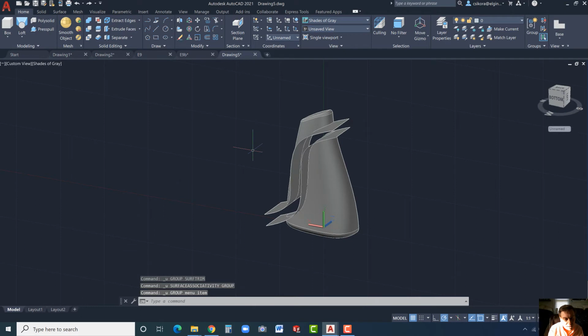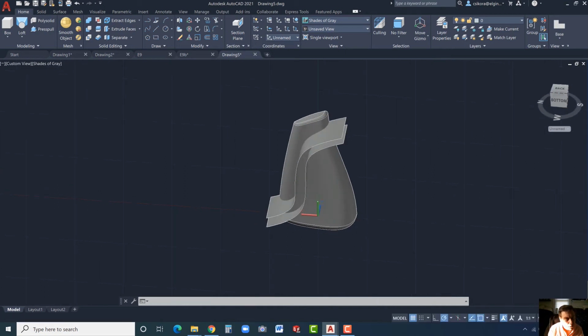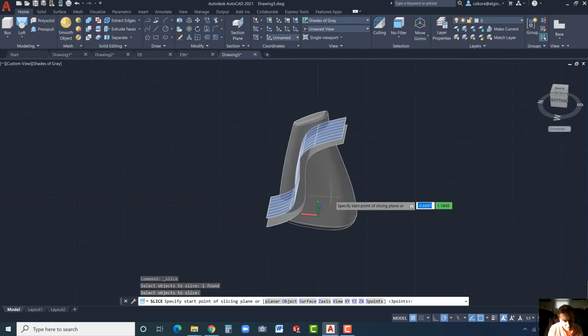I'm going to Control Z back. So I'm just holding Control Z, which is undo, until we get back to this. There we go. And I'm going to use a split instead because that seems to be a much easier method. So let's go to Slice. All right, Object to Slice. That's what we want. Hit Enter, and select Surface.